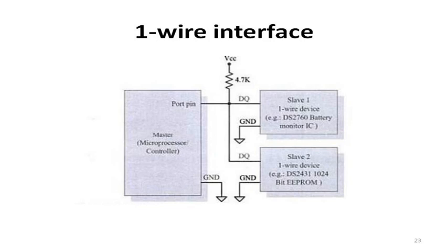In 1994, the application note explained that the only serial port interface options for one wire devices with a microcontroller port pin were UART and UART based communication ports. Since that time, special driver chips have been developed for direct connection to UART, PC bus or USB port.